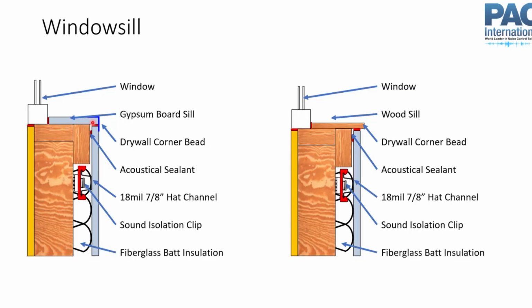So this is one of those things where we're going to make an acoustical compromise. And so this probably, your sill needs to be rigidly attached to this. But we want to still minimize that area that's rigidly attached. So this bit down here, we're going to float up here, and we're going to put some blocking back here. We're not going to attach it to it, but this is going to minimize the potential movement of this. So if somebody comes and leans up against this or something, it doesn't get pushed back. And this is also to support this so we don't have this cantilever. Like, we could move our isolation up here, but then this would be cantilevered out. And if somebody comes and sits on the edge, it's going to crack, right?